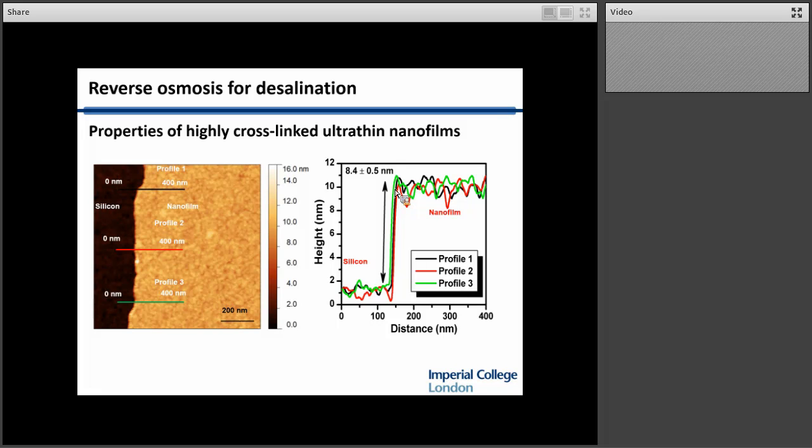Up to now, people have stated that the thickness of reverse osmosis membrane thin films are in the region of 50 to 100 nanometers. And what they're really measuring is the top to bottom thickness of that rugose rough layer. But what we think the membranes comprise is these very thin films that then crumple up. So the real thickness of the separating layer is less than 10 nanometers.